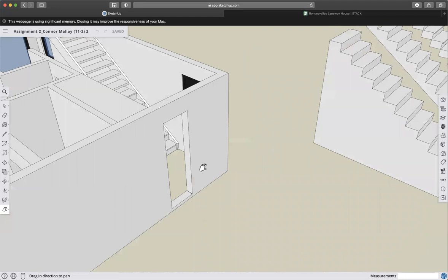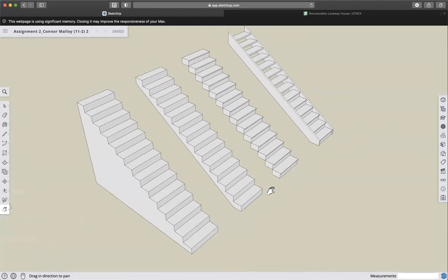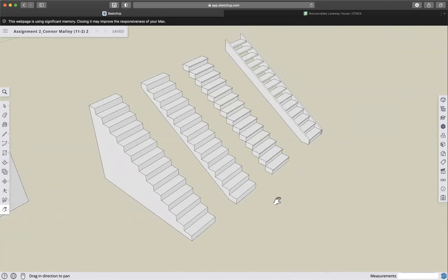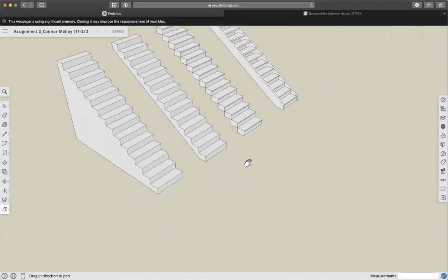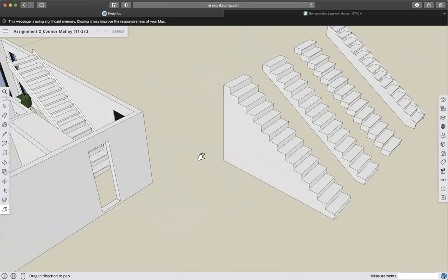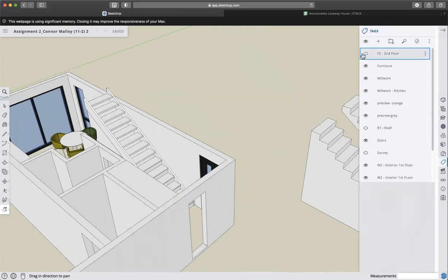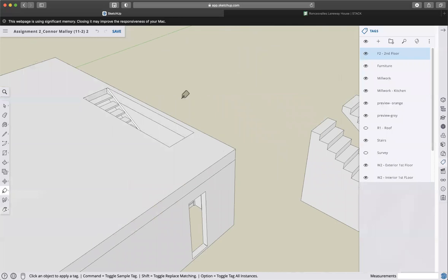So there are a number of ways we can build stairs. We'll review a few different ways and really emphasize the tools that you can use. We'll start just by drawing first the floor plate of what the stairs look like. So when I went to my model here, I measured the distance of the floor opening in our floor. If I turn the floor back on, I took my tape tool and measured my opening. My opening is 3'1".